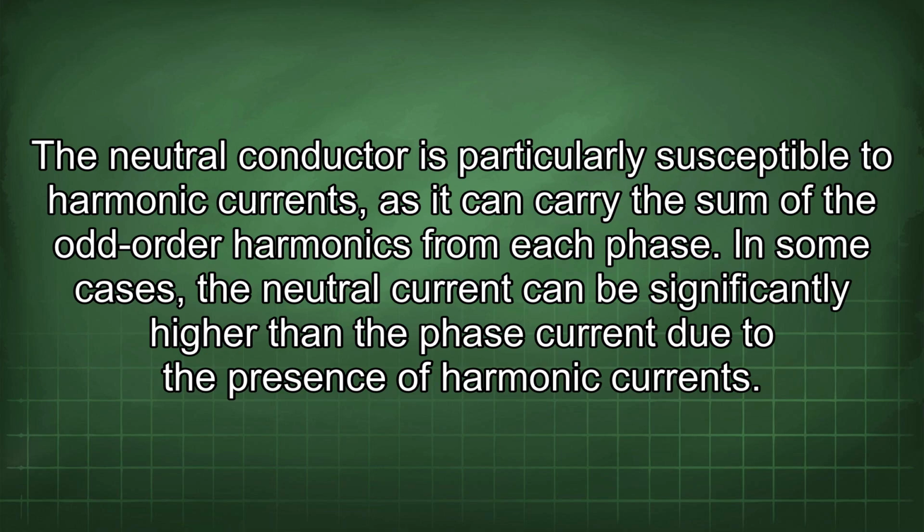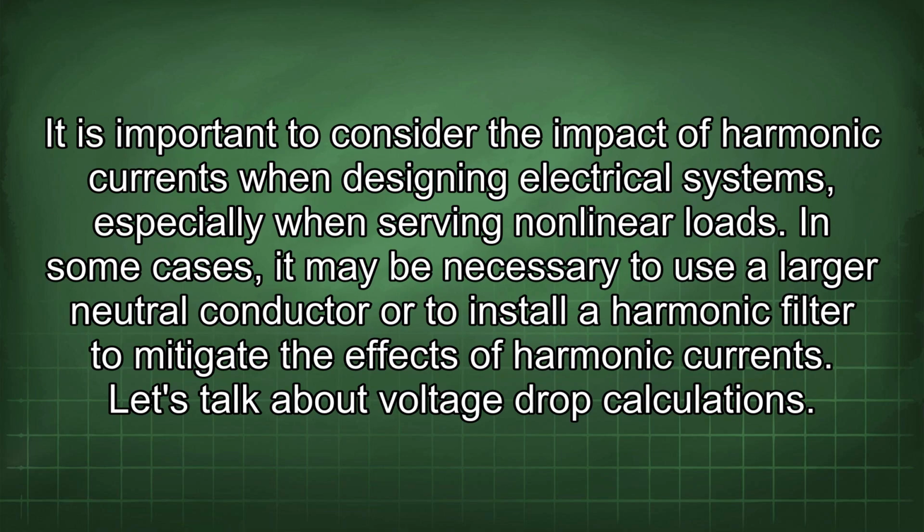In some cases, the neutral current can be significantly higher than the phase current due to the presence of harmonic currents. It is important to consider the impact of harmonic currents when designing electrical systems, especially when serving nonlinear loads. In some cases, it may be necessary to use a larger neutral conductor or to install a harmonic filter to mitigate the effects of harmonic currents.